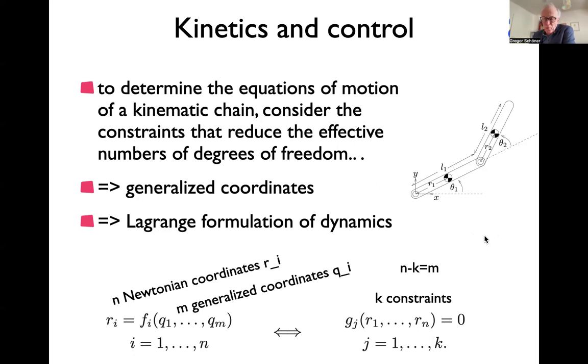And the problem for robots is that there is this big difference between their degrees of freedom as rigid bodies, when they're free, and when they're mounted in a chain. They have constraints. When they are rigid bodies in the 3D world, as I mentioned before, they have 6 degrees of freedom, translational and rotational. We know Newton's law, the inertial law, so we can write down the equations of motion in terms of Newton's law, and then we get a lot of equations. But when we mount them in a chain with revolute joints, all these degrees of freedom are now constrained.